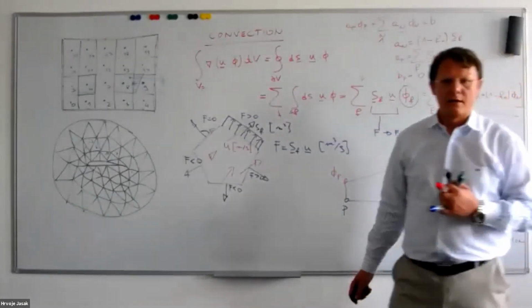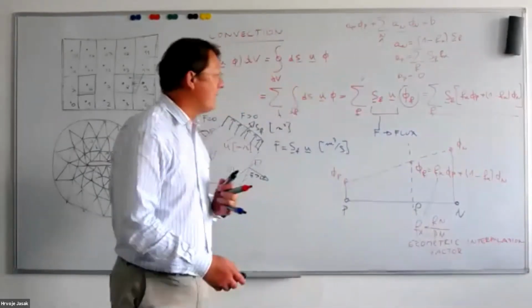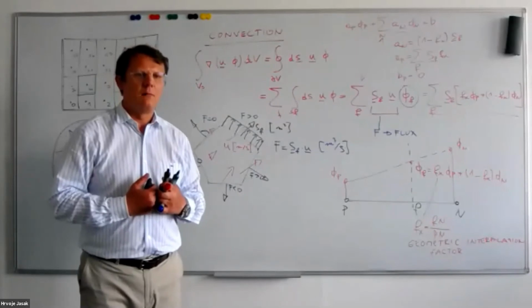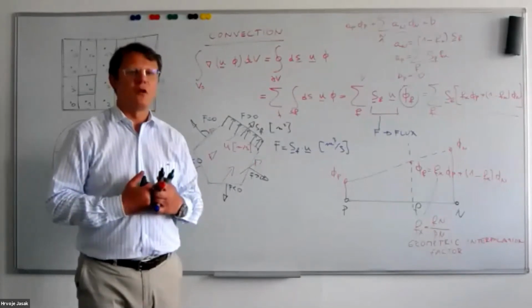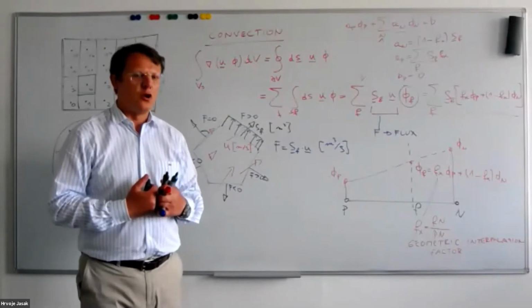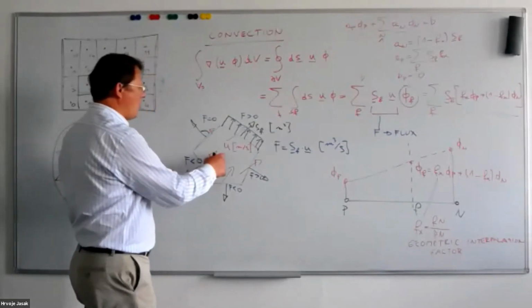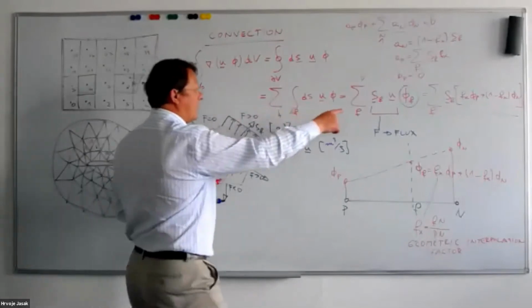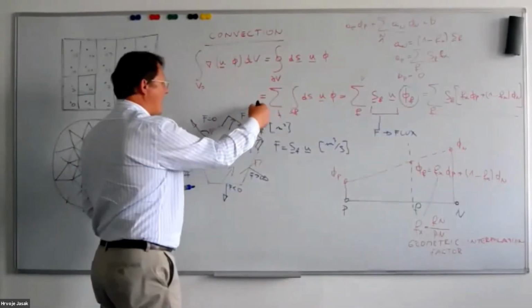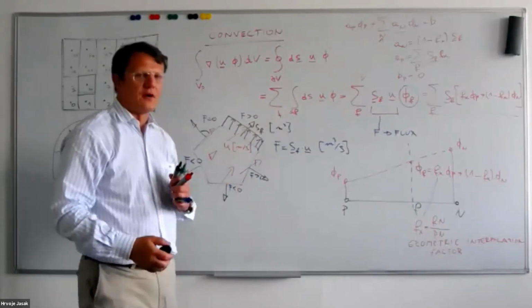Unfortunately, the second order accurate convection discretization scheme is a nice idea, but it suffers from a lack of transportive properties. Notably, you will not know, based on the interpolation that I have written out here, whether the flux goes in one direction or in the other.